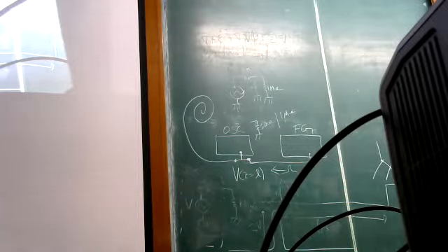Yeah, I mean, it's drawn in front of you, right? So what's going to happen? The pulse arrives from the function generator to the oscilloscope the first time. And at that time, the scope will display a pulse, but now half the amplitude of what it was when that extra cable was not there. And then what happens?